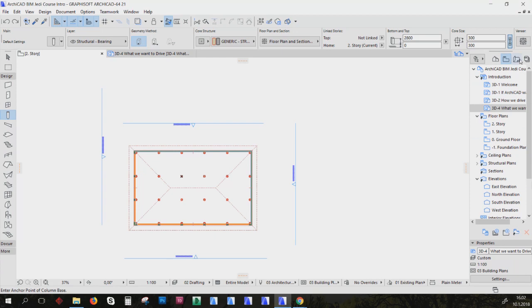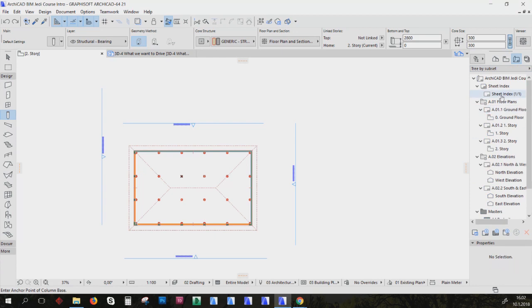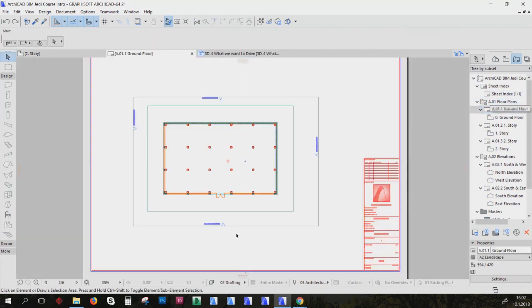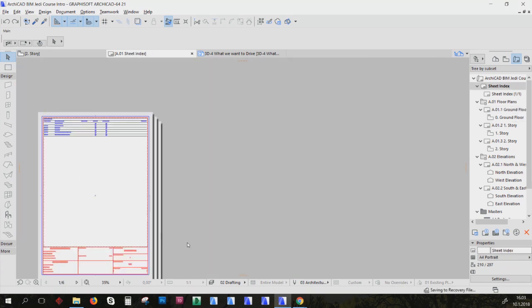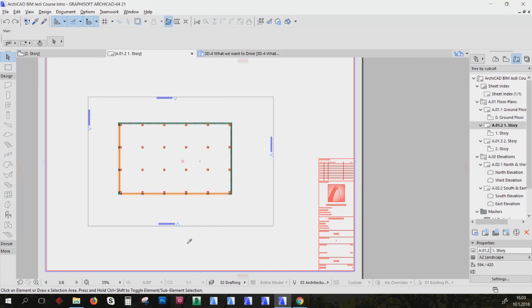If we go into the layout book, say ground floor plan, instead of having to go across here to choose your layout each time you want to move, there's this one down here, and also Control Alt left and Alt right. So Alt right will take us down there, and Alt left will take us there. Alt left and Alt right, or Option left and Option right.